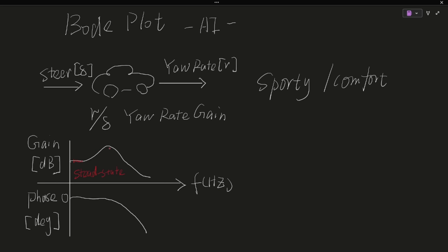And at a specific frequency here, the yaw rate gain reaches a peak value. This is called resonance frequency. The higher the resonance frequency, the more sporty the vehicle.